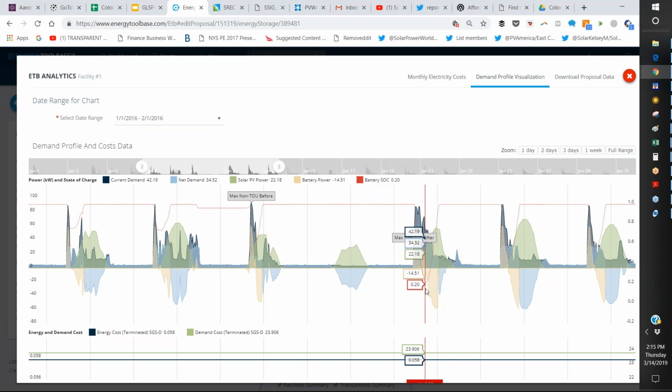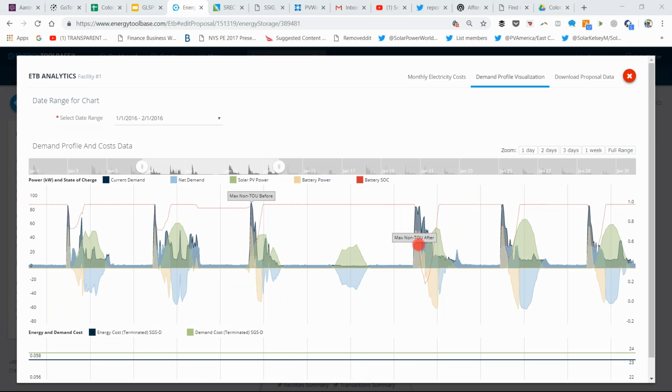And it gets to the bottom and it can no longer do load leveling. And so that's just enough for my solar array to turn on. So I got kind of lucky there. And so then I go back and I look at this and I say, okay, well, I'm looking at my new load profile right here in light blue. And what I'm seeing is that here in light blue, it's kind of a plateau. And so I am getting into that diminishing returns where I have this other base plateau and then my off-peak plateau. And like this is as far as I can do for load leveling.